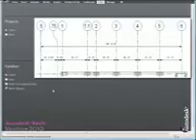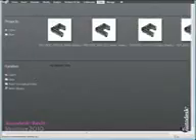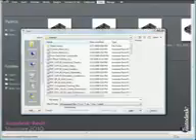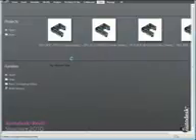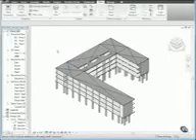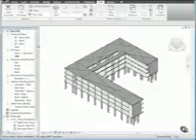During this lesson, you will dimension the grid lines on the north side of the structure. Click the menu browser and select Open. And in the Open dialog, from the Training Files Imperial folder, open the file rstdocad01, create dimensions. Then open the view 01 entry level,